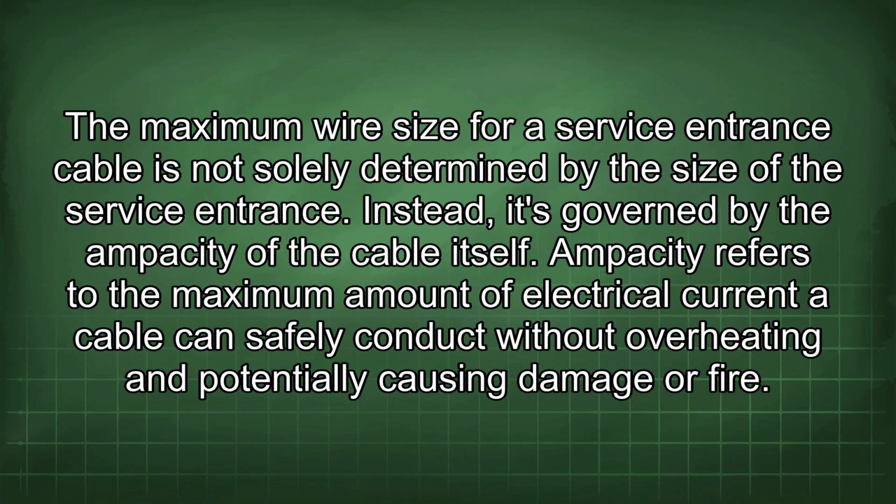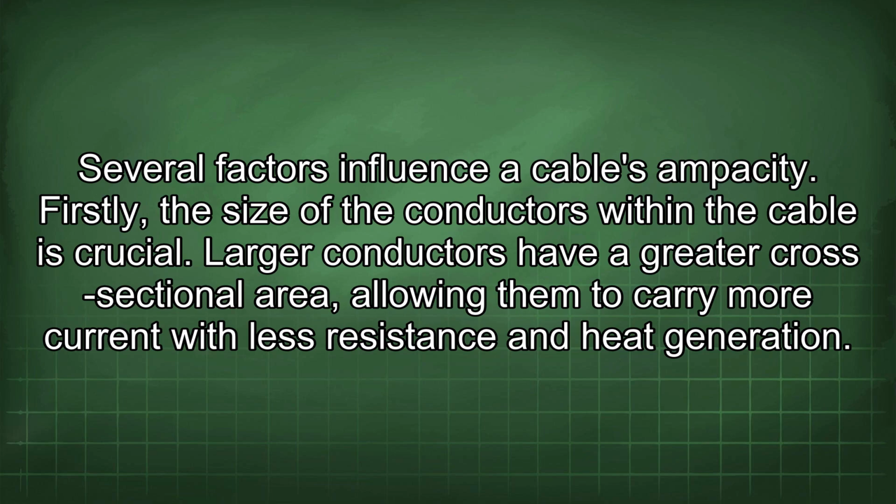The maximum wire size for a service entrance cable is not solely determined by the size of the service entrance. Instead, it's governed by the ampacity of the cable itself. Ampacity refers to the maximum amount of electrical current a cable can safely conduct without overheating and potentially causing damage or fire. Several factors influence a cable's ampacity.